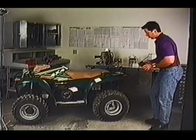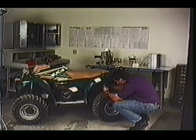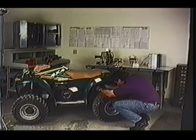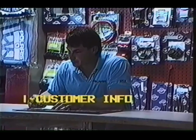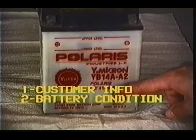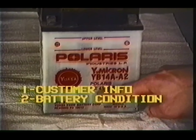When faced with a difficult charging system problem, try to isolate the problem from the rest of the system. Is it a battery problem, system load problem, or alternator output problem? Let's recap the tests we've discussed to help find these problems. Get accurate and complete information from the customer and note it on the repair order. Check the condition of the battery. Look for signs of sulfation or corrosion. Make sure all connections are clean and tight.